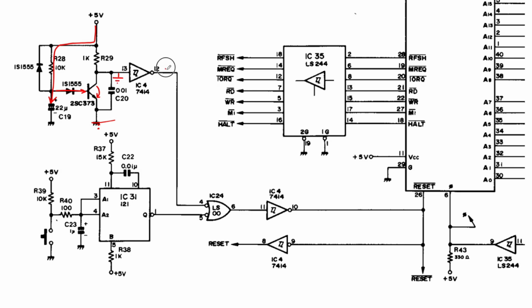And therefore, the output will be a 1, and then the computer comes out of the reset state. That's how it's supposed to work. The way this could fail is after you've charged this capacitor, if there still is no positive potential here on the base and the transistor doesn't close, then you keep putting the 5 volts on the input of the inverter, and then the output will be at ground, and the computer will be always in reset.